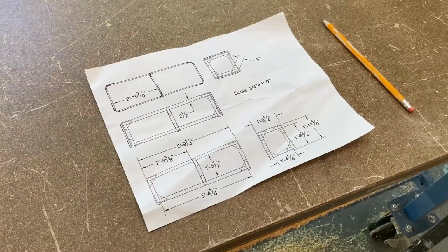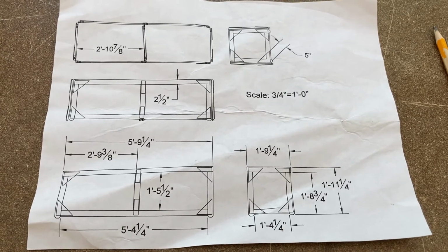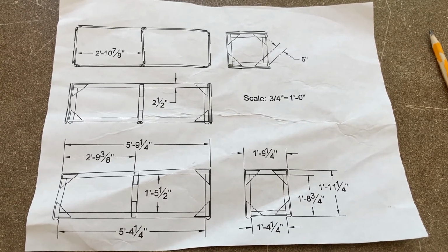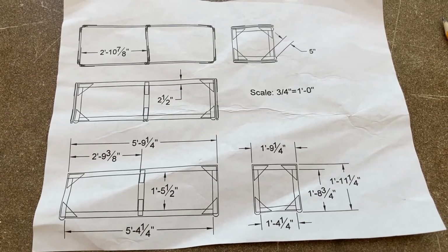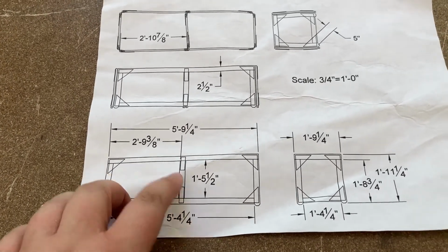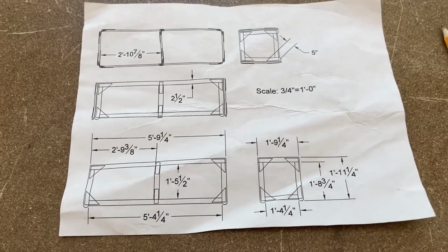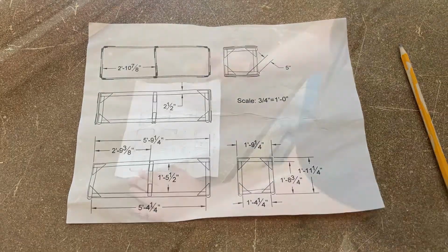So I brought along a copy of my very quick drafting of what we're doing. I don't really need it for building, but it's a great idea to have a copy just so I can reference it when I'm making my cut list, which is basically the list of lumber pieces I'm going to generate for myself that specify how many pieces I need at 1'5" and how many pieces I need at 5'9". It helps you keep track of what you're doing, especially when you get into mass production and you're building many of these things.